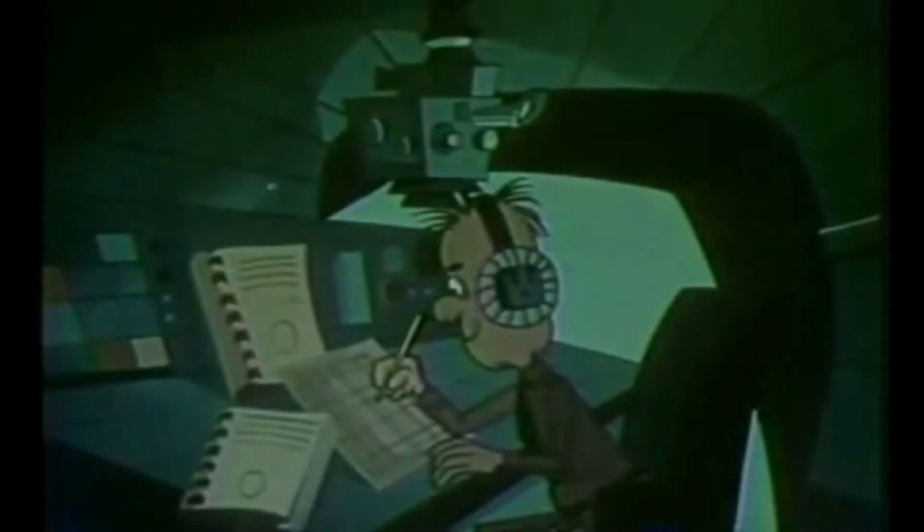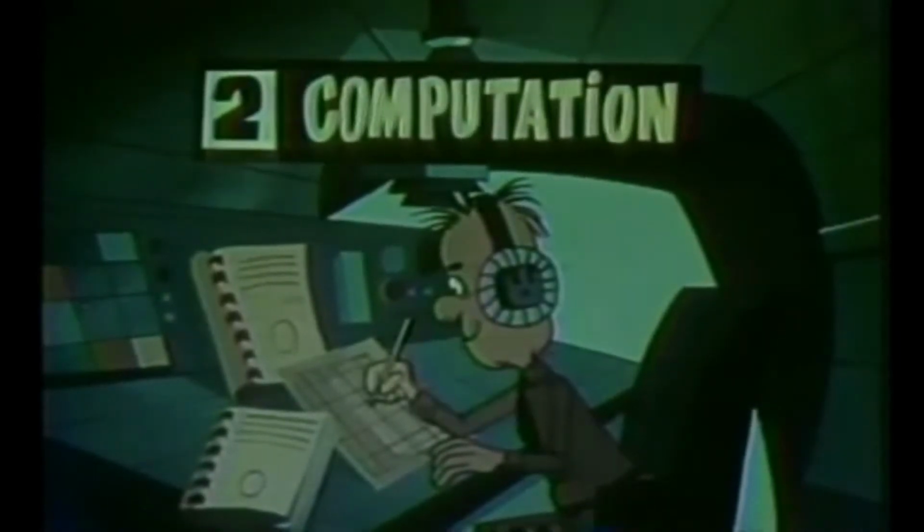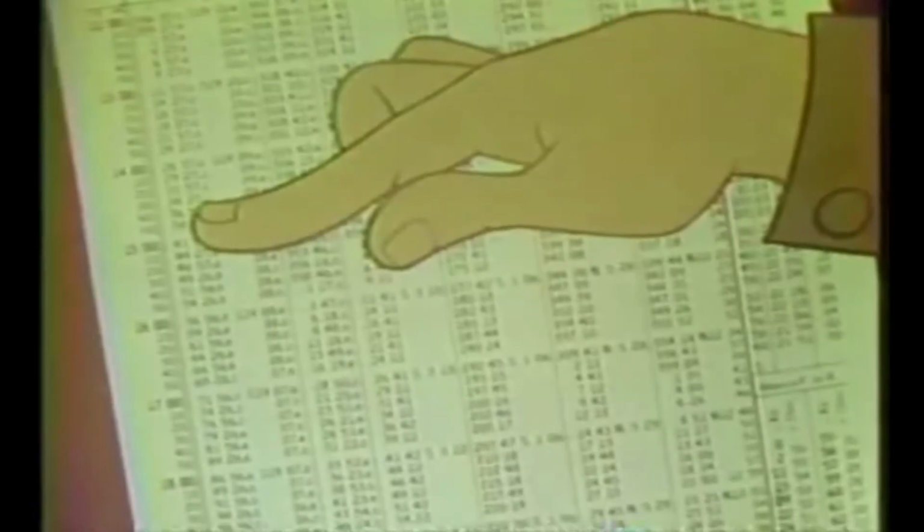Now you're ready for the computation stage. Remember, you will be using tables to solve a celestial triangle. To do so, you will need to know the declination of the observed body, the sun, the latitude of your assumed position, and the local hour angle between them. To begin, you turn to your air almanac. Open to the page for January 24.